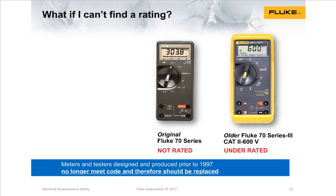Okay, so you have an old piece of equipment. It works fine. It's an older meter, typically before 1997. They didn't have the CAT ratings. So the question becomes, should I replace that? I mean, it still works. Its resolution, its accuracy seems to meet my requirements.